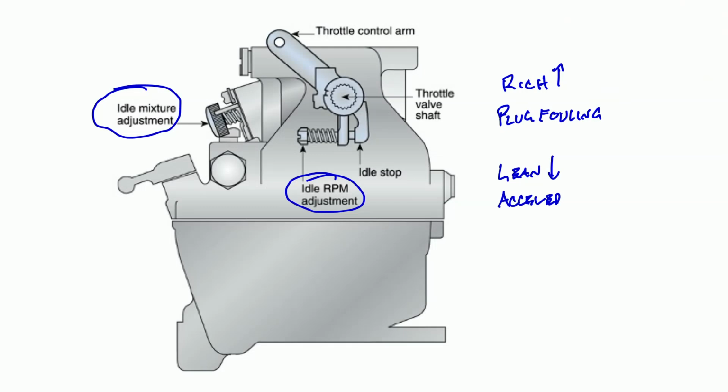So as the aircraft is running at low RPM, we're scheduling way too much fuel into the idle circuit, and it's just loading up carbon and unburnt fuel and lead onto the spark plugs, and then we start getting spark plug issues or ignition issues, which we can spend a lot of time troubleshooting if we don't know what we're looking at. So making sure our idle mix is adjusted properly helps an awful lot with plug fouling and making sure that it runs properly.